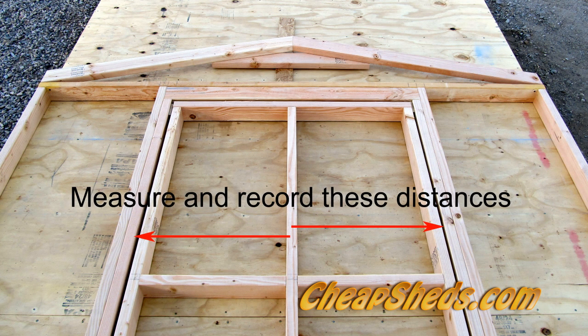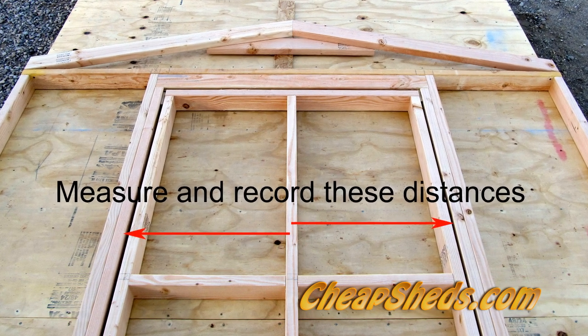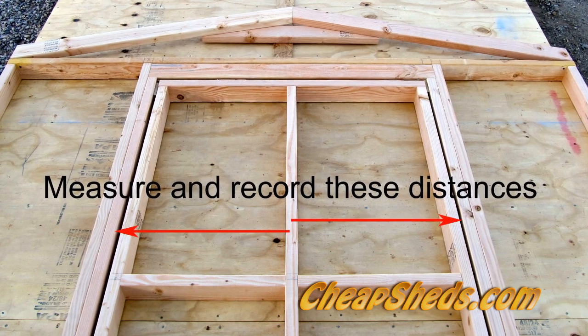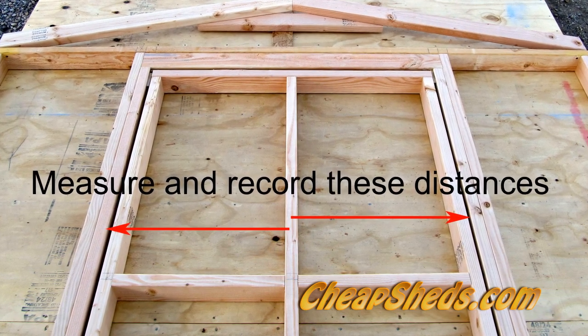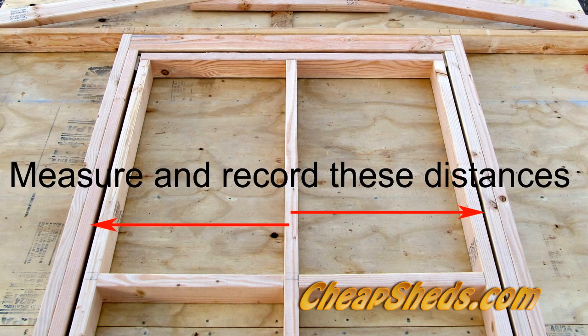Measure and record the distance from the center of the stud where the siding breaks to the inside edge of the rough opening in both directions. This measurement should be 21 3/4 of an inch for 8 and 12 wide shed doors, or 9 3/4 and 33 3/4 for a 10 wide shed door. These measurements will be used to locate the vertical cut lines after the siding is nailed in place.